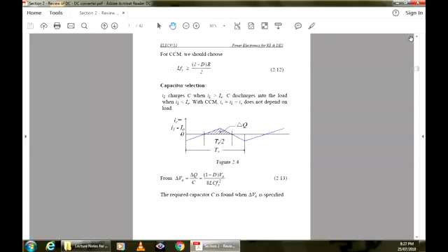That's how the inductance and capacitance are found. This gives you the L, for the minimum load, meaning the highest resistance. And this gives you the C for the acceptable capacitor voltage ripple. That's how we obtain the parameters of that converter.